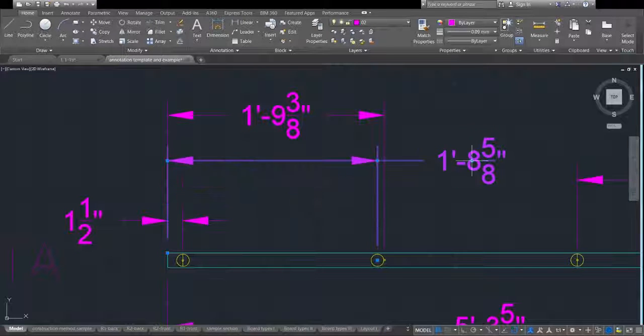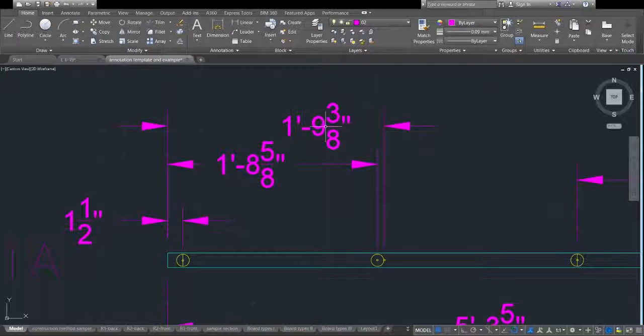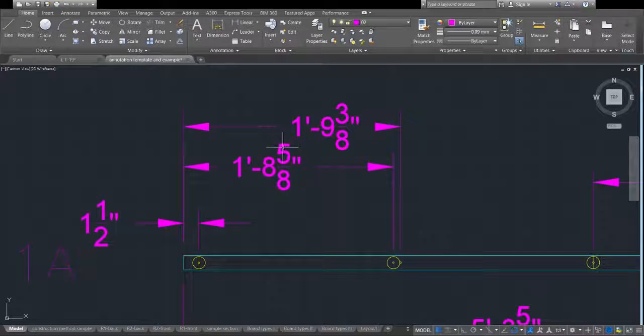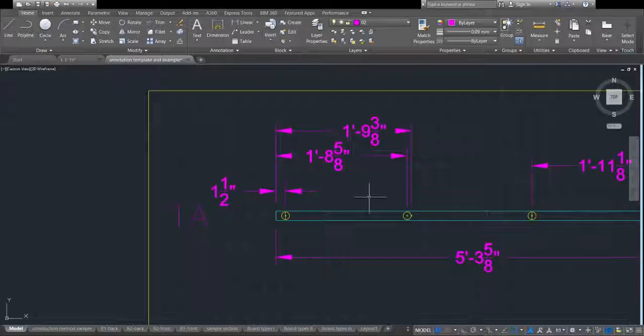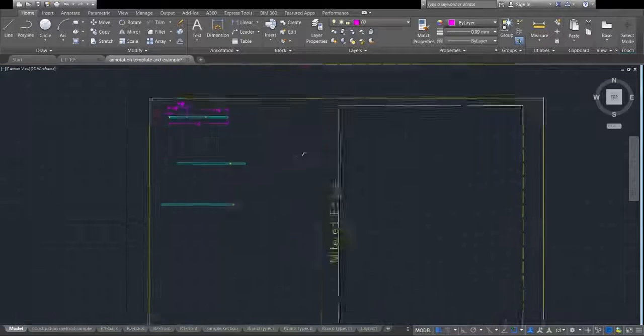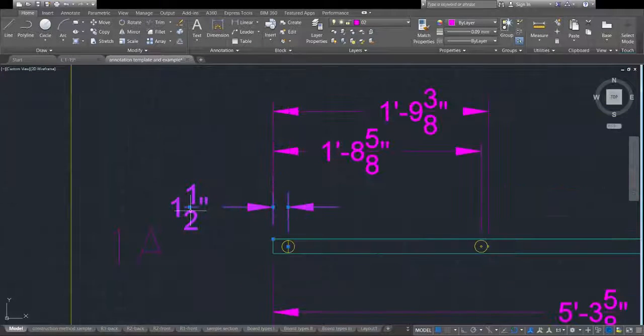One trick you can do is, if you have something stacked like this, to get the dimensions a little bit closer to one another, you can put one on the left and one on the right, and that lets you share a little bit of vertical space, and it's still perfectly readable. And that becomes important when you have like 8 beams in one list. It just becomes a lot easier to get all of those beams in on the same page when you're saving space like that.